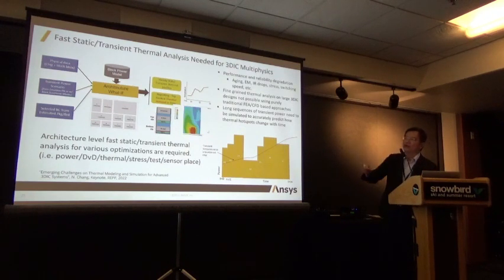This is the request from customers: given the transient power vectors on chip with block placement, how do you provide very fast dynamic thermal simulation at all locations with a 10 micron mesh grid resolution? This is entirely a machine learning problem, because using the finite element method, the simulation would take more than 3 days.